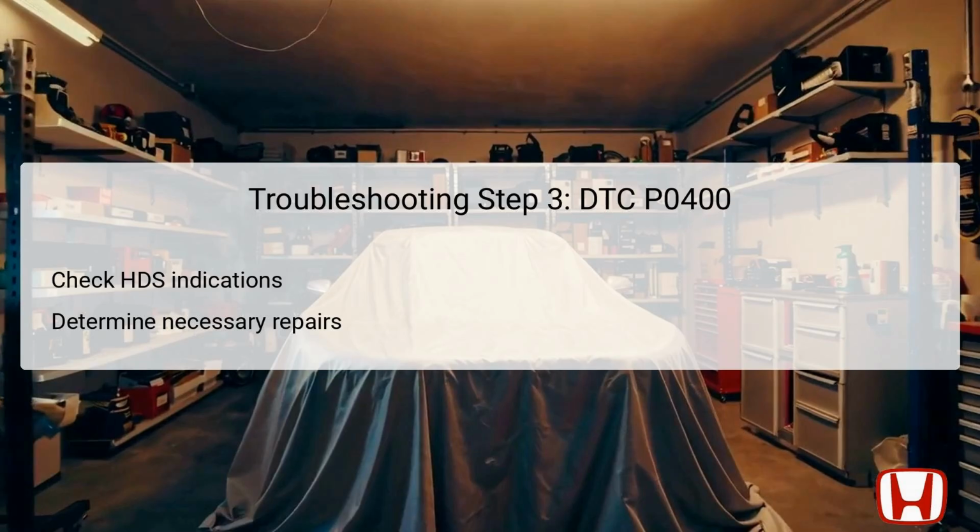At this stage, checking for any exhaust gas leaks between the EGR pipe and the EGR valve is critical. If the HDS reports not completed, it suggests the system has not met testing criteria, and you may need to revisit Step 2 to ensure all conditions were adequately established for a comprehensive test.